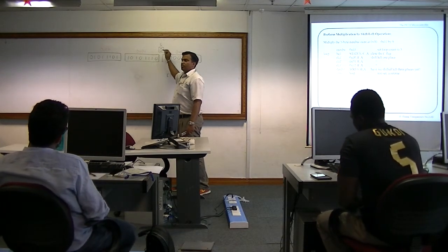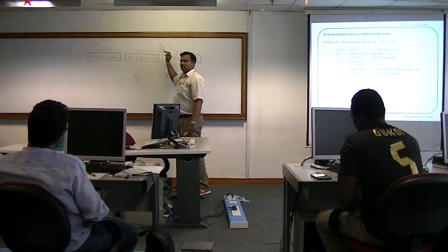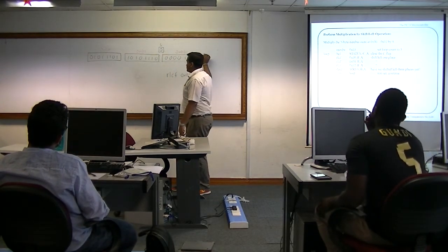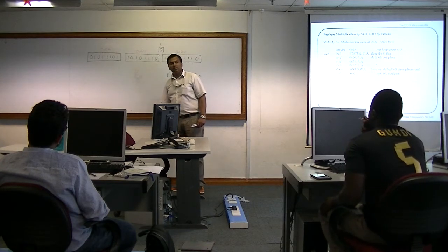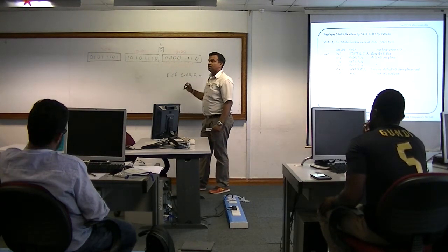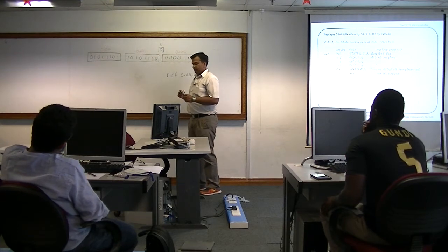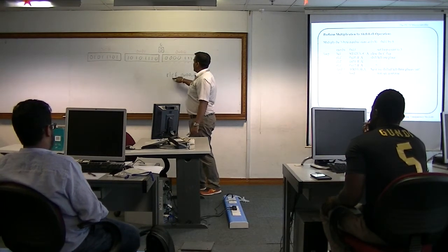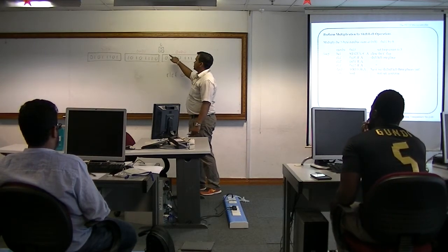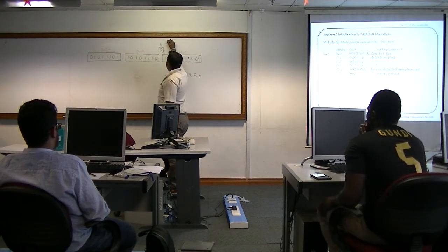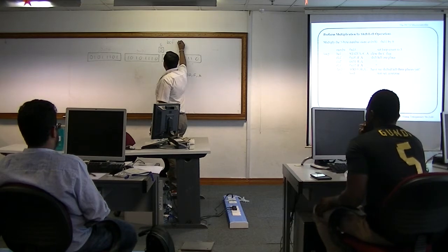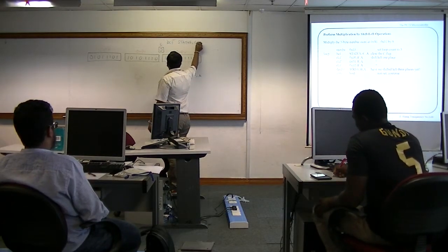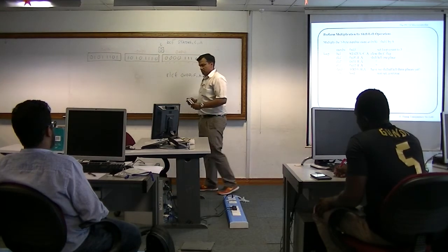So you always have to do bit clear F status register comma C. Each time you need to make sure that the carry value that enters the least significant bit is 0. You understand? So when you do rotate left through carry, before you do this you must do bit clear F status register C. You must always do that.